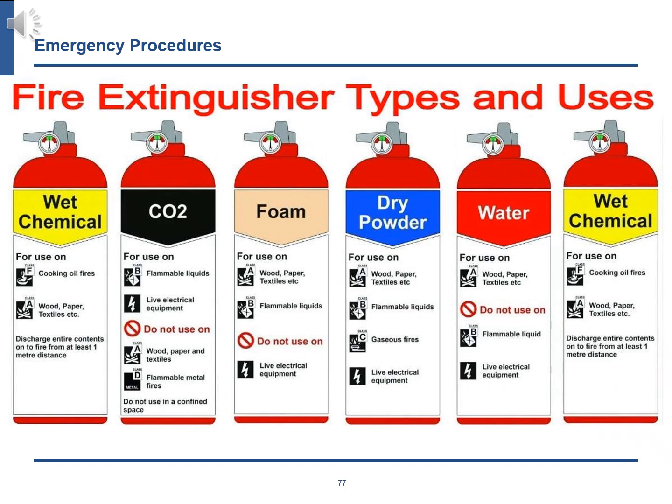For electrical fires involving live equipment, it's crucial to use the correct type of fire extinguisher to avoid the risk of electric shock. Suitable fire extinguishers. CO2, carbon dioxide, extinguishers are ideal for electrical fires as they do not leave any residue and do not conduct electricity. They work by displacing oxygen, which helps to smother the fire. Dry chemical powder extinguishers contain non-conductive chemicals that can effectively put out electrical fires without the risk of electric shock.